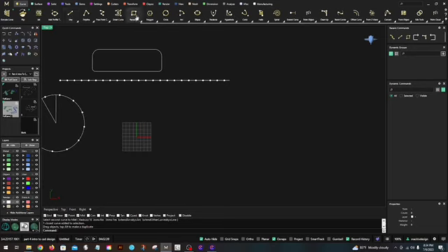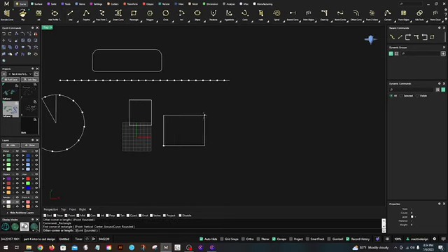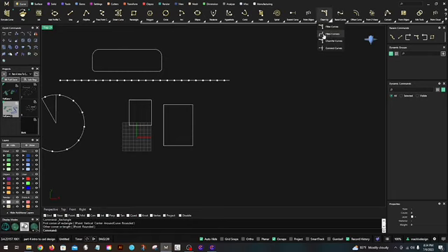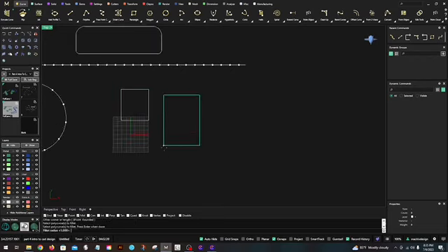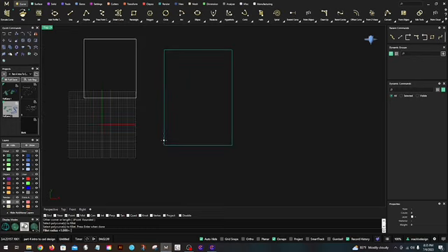All right, let's go ahead and bring in some more rectangles and see what else is on here. Fillet corners. Okay, this one I believe, oh yeah, this one is all 4 corners. So I'm going to press fillet corners and select my curve to fillet. Press enter when done.